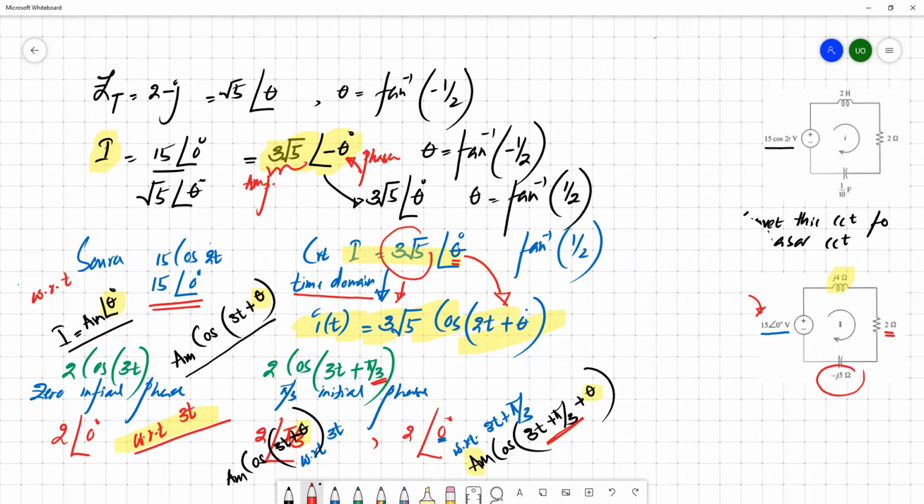How do we convert into phasor and manage to convert back into time? So the summary is, if you are given a time domain circuit, you can simply convert it into the phasor domain to evaluate the forced response basically. You can't evaluate the natural response from this, because natural response is simply because of the initial condition. So then definitely you have to solve the differential equation. So we'll keep that part aside and focus on forced response.